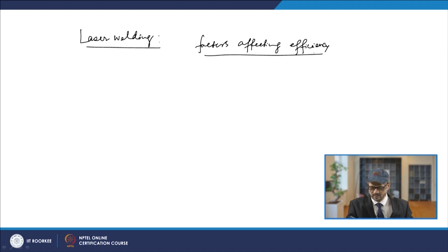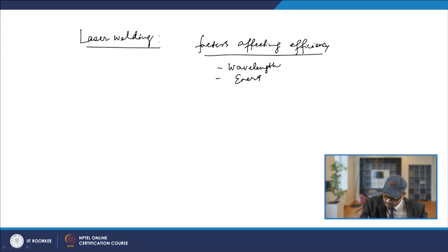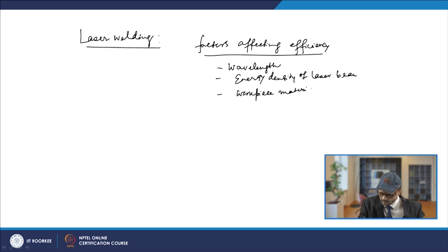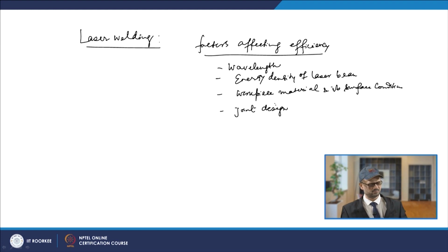So, it will be the wavelength, then you have the energy density of the laser beam, the workpiece material, its surface condition, and joint design. Basically, the efficiency of laser welding will depend on all these factors.